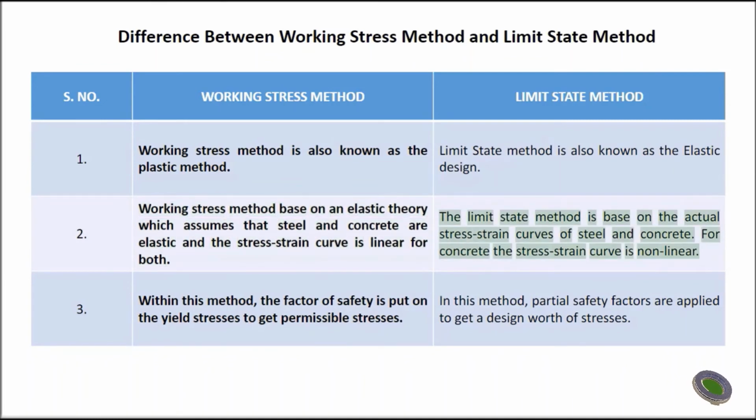The limit state method is based on the actual stress-strain curves of steel and concrete. For concrete, the stress-strain curve is nonlinear. Number 3. In this method, the factor of safety is put on the yield stresses to get permissible stresses. In this method, partial safety factors are applied to get design values of stresses.